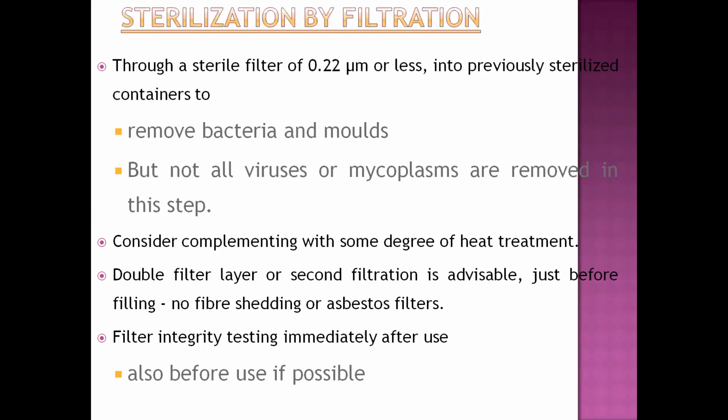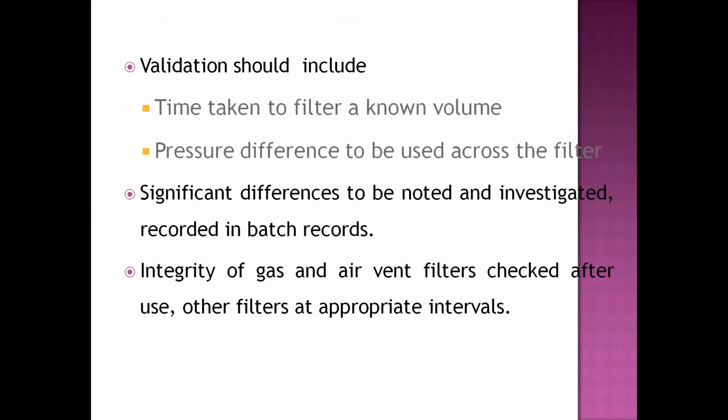Then consider complementing with some degree of heat treatment. Then a double filter layer or second filtration is advisable just before filling, with no fiber shedding. Filter integrity testing immediately after use, and even before use if possible.